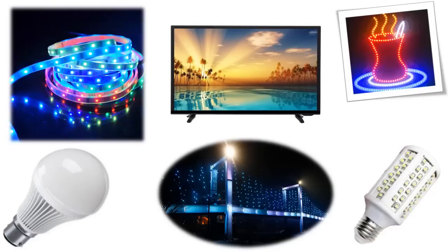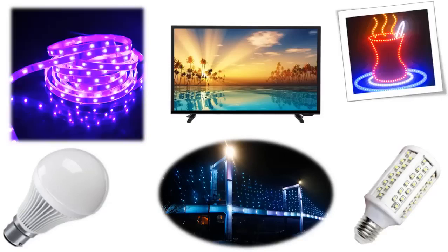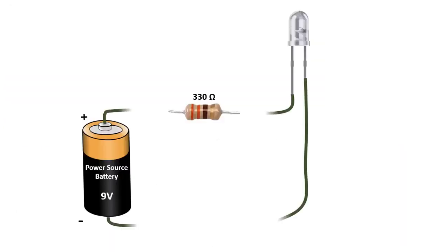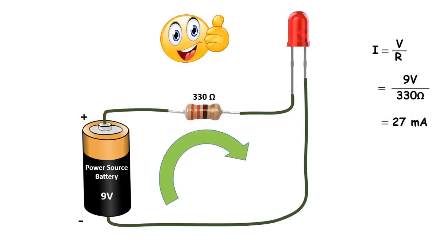The first indicator that the LED will have is a longer positive lead (anode) and a shorter ground lead (cathode). The other indicator is a flat notch on the side of the LED to indicate the positive anode lead. Like all diodes, LEDs create a voltage drop in the circuit, but typically do not add much resistance. In order to prevent the circuit from shorting, you need to add a resistor in series.